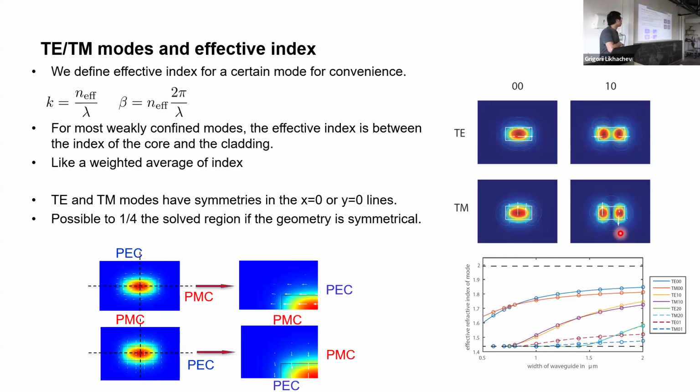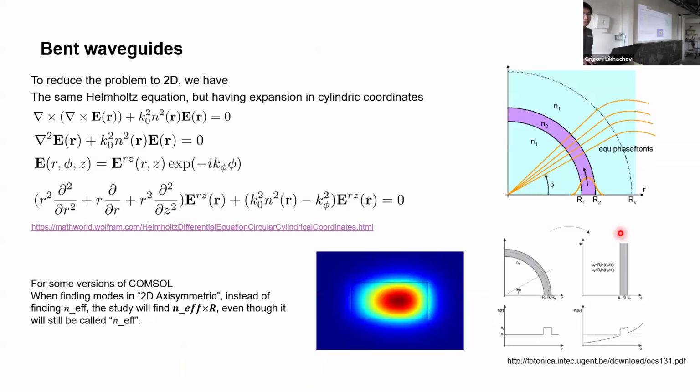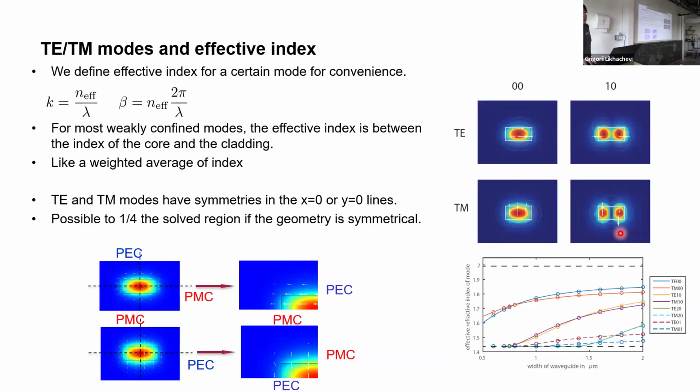And also, if you refer to the fiber literature, they have a very different kind of mode nomenclature. I mean, they just name it differently. And actually, they're called quasi-TE and quasi-TM, because it's never truly horizontal or truly vertical. Just to distinguish them, we name them TE when it's mostly horizontal, and TM when it's mostly vertical. Yeah, thanks for the explanation.